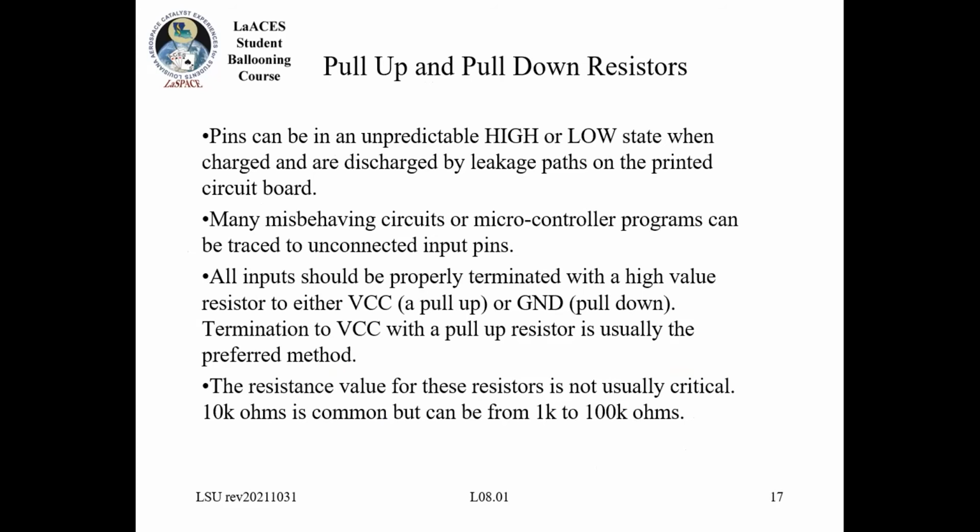If I didn't have a connection to ground or a connection to a positive voltage, those pins would be in some unpredictable state. It's really easy to see this if you try to read the state of a pin that doesn't have anything connected to it. You just get random values.